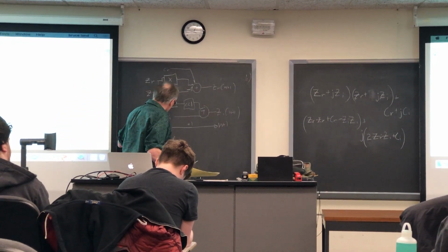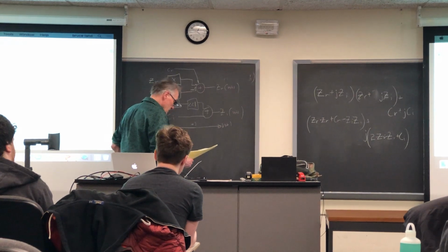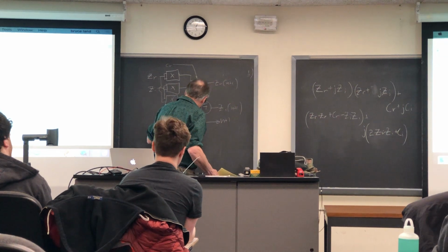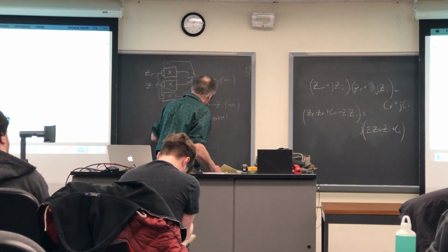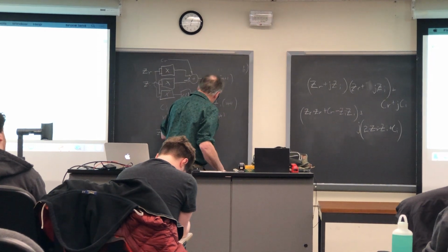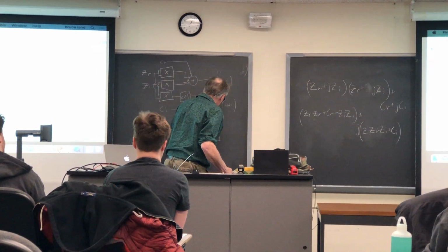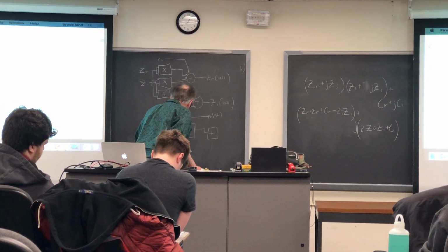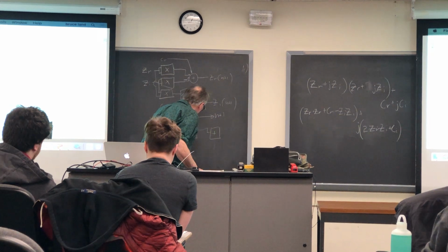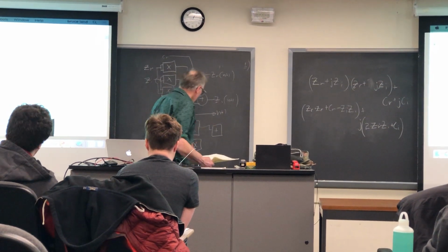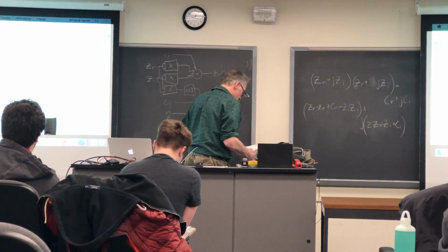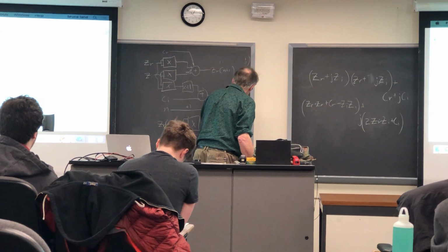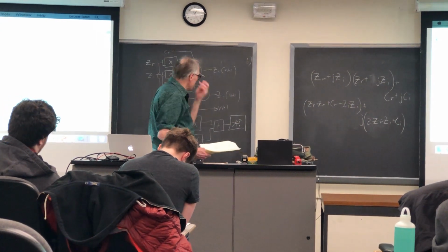Then we're going to take ZR n plus 1 that we've just calculated up here, feed it twice into a multiplier. Add it to ZI n plus 1, another multiplier into the adder. And ask, is this greater than 4?